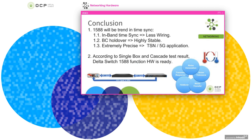The second one is, because here we use the boundary clock to achieve 1588, it retains a center time with a very stable OCXO, so it could hold over very stable. It means you have a highly stable system when using a boundary clock.